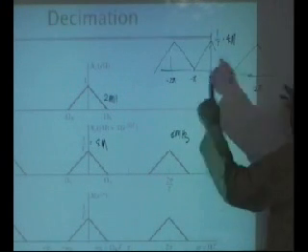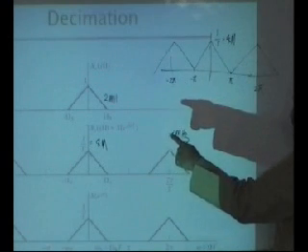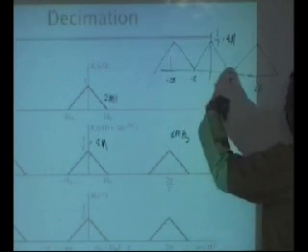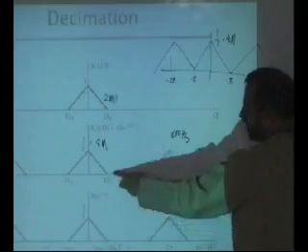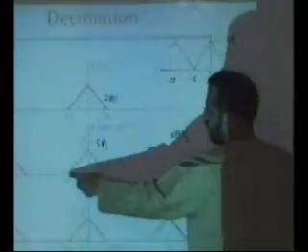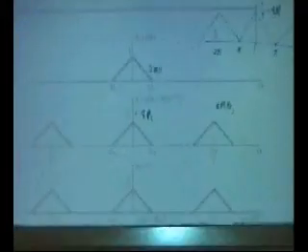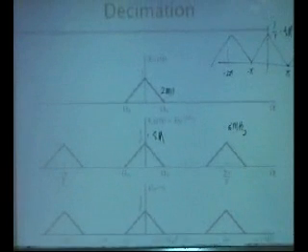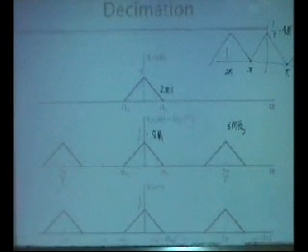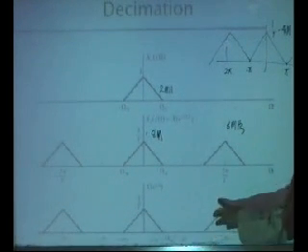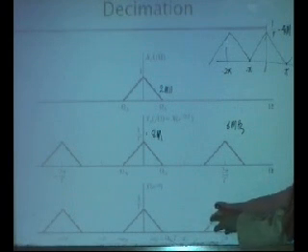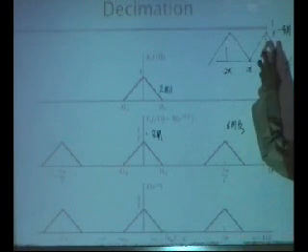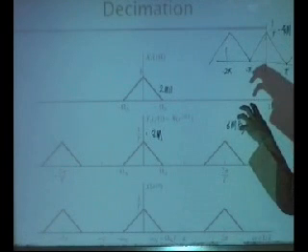The spectrum will spread to minus pi and pi. If you are doing more than what is required, you will find some space here, as is shown in this case. So the important thing is that once you throw away samples, your digital spectrum, which is this, will again map to this. This is guaranteed.